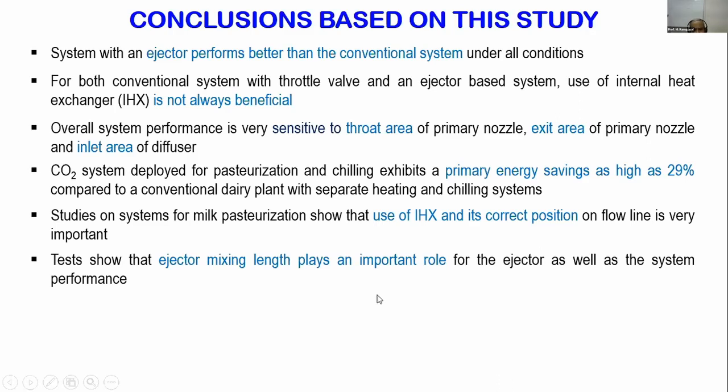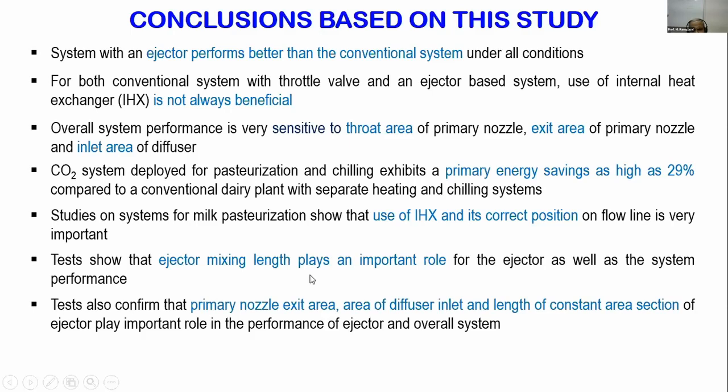Now there are a lot of theoretical models, and people are also using computational fluid dynamic tools for designing the ejectors. There are different types of models. The model that we have used for design of ejector is based on the homogeneous mixer, but we have considered the compressibility effects, etc. We assume that the two-phase mixer is a homogeneous mixer. When we compared the theoretical ejector performance with the experimental ejector performance, the difference is not too much, maybe about 25 to 30% or so. So we thought this model is not very bad.